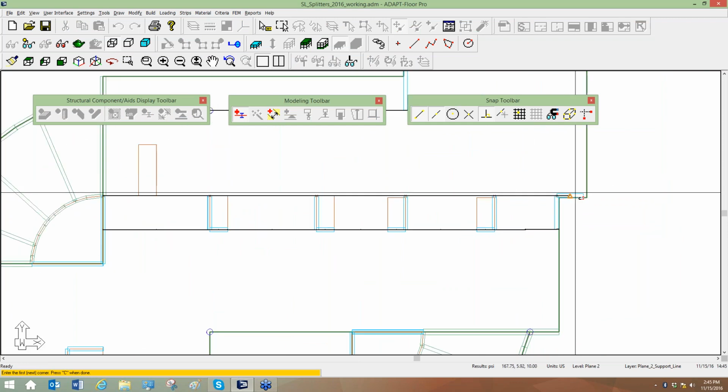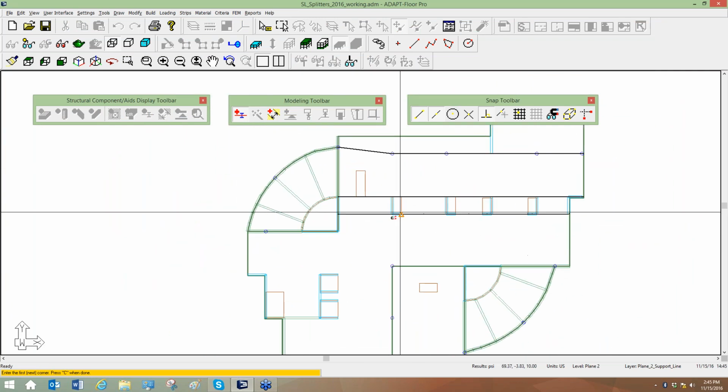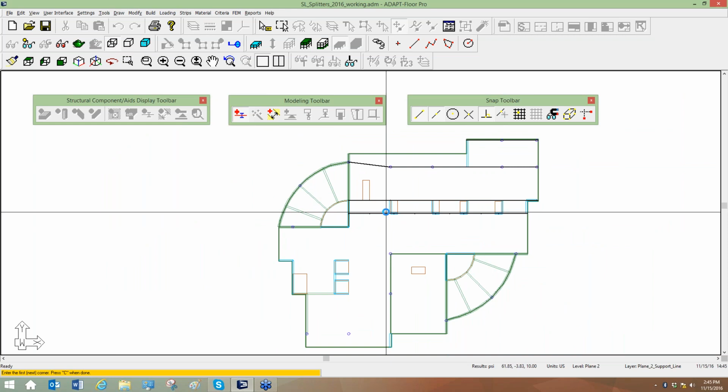When we have a post-tension slab, it's recommended, I would follow the direction of the tendons, the banded tendons in one direction. In the other direction, we want to follow more orthogonal layout of support lines. The reason we want to follow the banded direction is the tendons that intersect design sections along that band will have primary effect if they're perpendicular to the section.